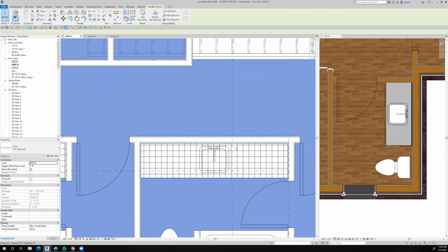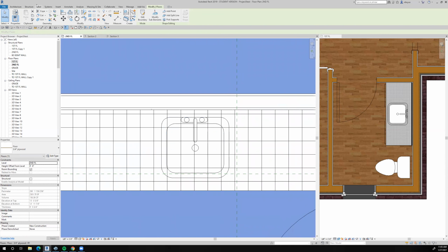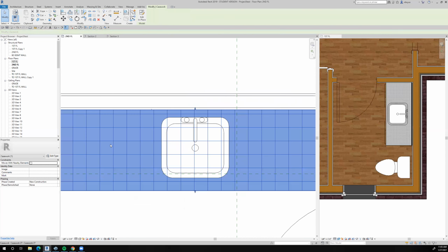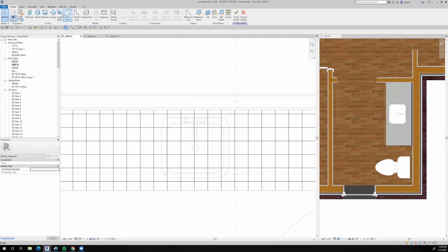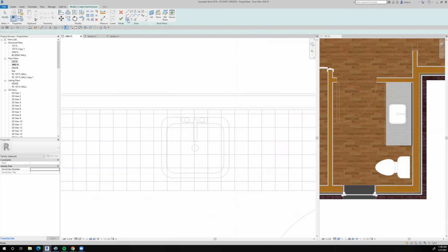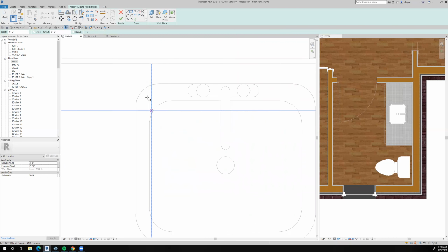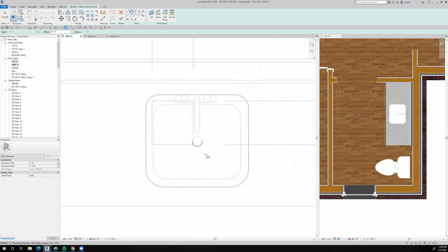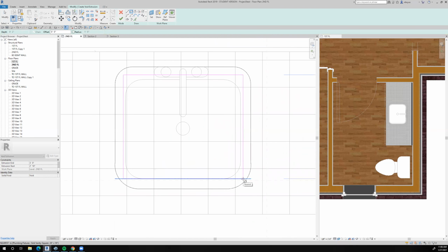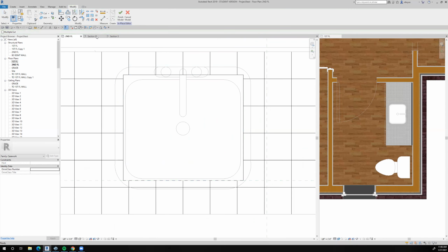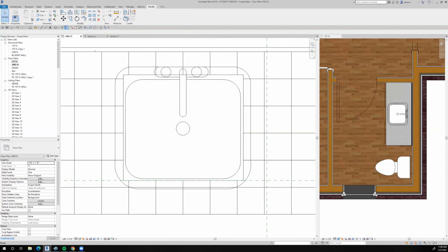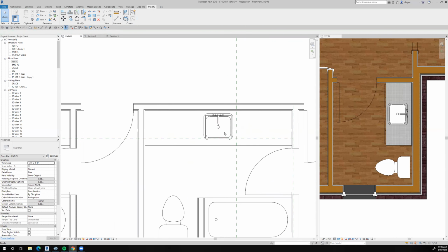And so now let's go over here and do the same thing. Click on the extrusion, edit in place, create a void form, and we'll try that rectangle again and see if we can do it. That looks good. That's going to be outside, and that's going to be outside. We'll say okay. We're going to cut it, and we'll say okay. That looks good. All right, so we've got two now.